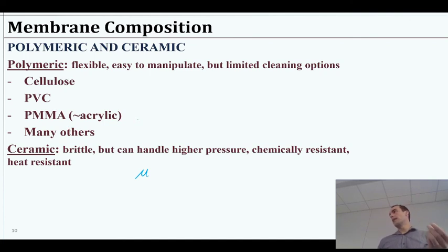It's less viscous, meaning that's actually probably an advantage for membrane filtration, right? It slips through the pores easier. So if you could keep it hotter, you don't have to pay as much energy cost for the membrane. You don't have to cool it first. So that's kind of another process advantage. So it's kind of an interesting project. I don't know if they are using it or not, but it seems like if they figured it out correctly, then they probably would.